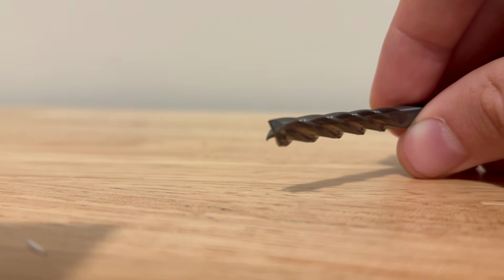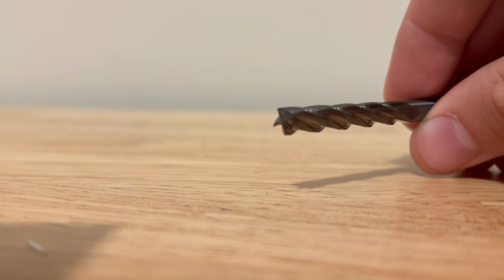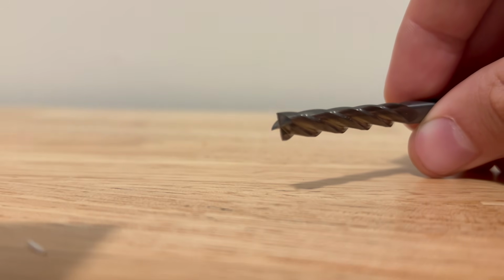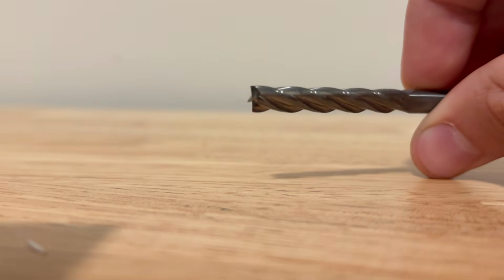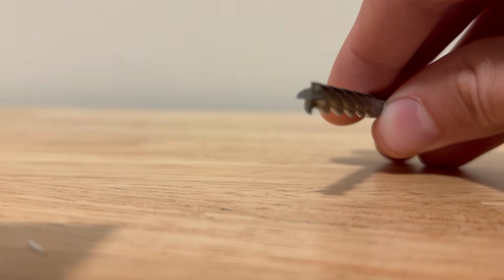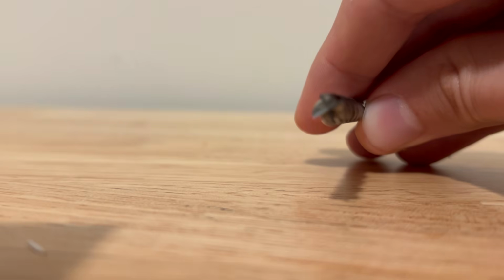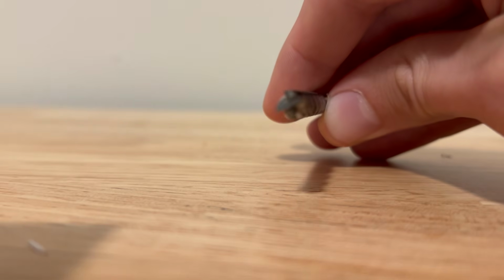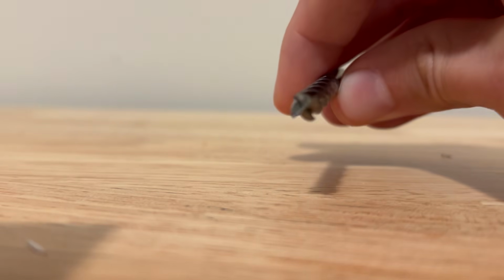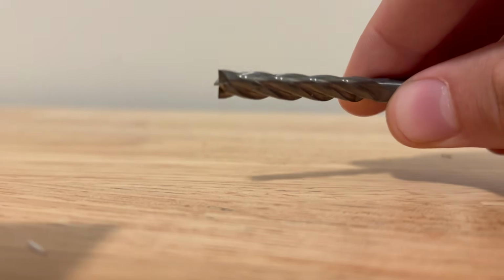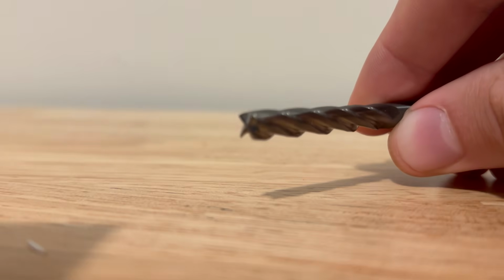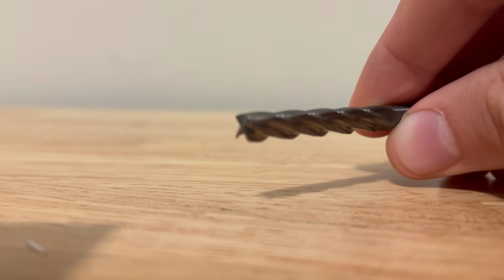For cutting steel, stainless steel, things like that, I'm not even going to touch titanium. If you're cutting ferrous metals or metals that have a high hardness and don't make large, stringy chips like aluminum, you're going to want a 4-flute end mill. The 4-flute end mill is more rigid, think of the drill, because there's less material removed by the flutes. So this is a more rigid tool. So why would you not use a 4-flute end mill on everything, since it's rigid and we're on a small machine and we're fighting rigidity all day?